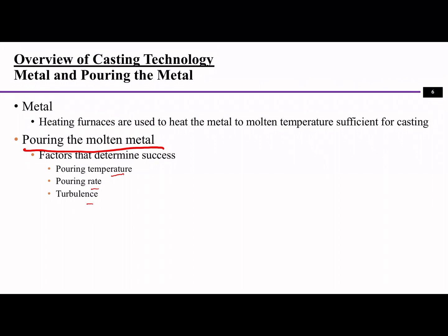If you pour at a different rate, say a different speed, what happens is that some of the material that you pour at the very beginning, when it is really fast, might solidify, and then later you pour at a slower speed, and the part in there has already solidified, and then you pour the molten metal onto it. It might also create parts where the material is not evenly distributed in the cavity, and they might create some cracks or air traps as well.